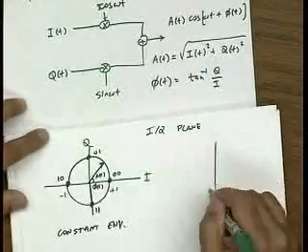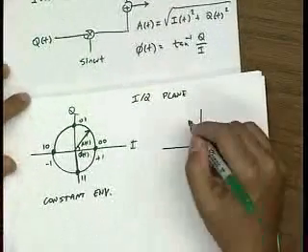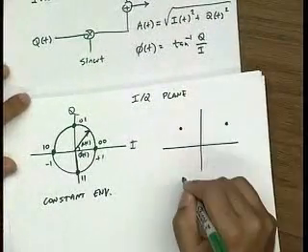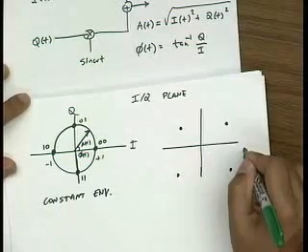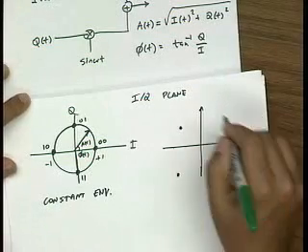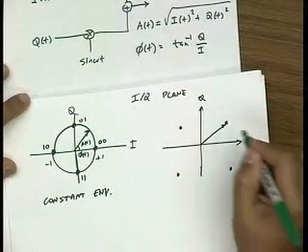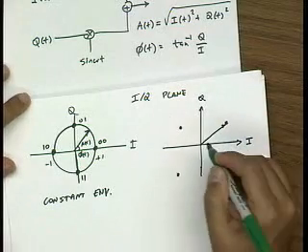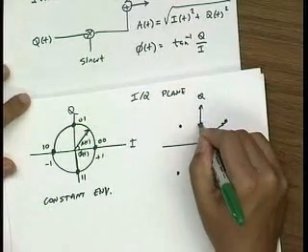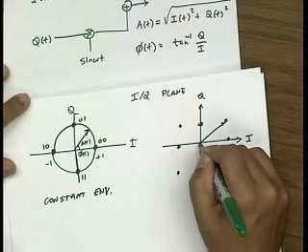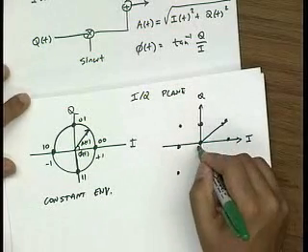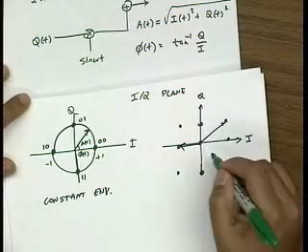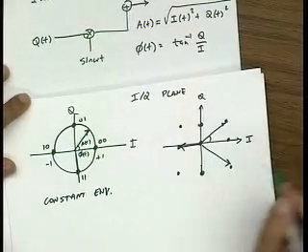I could also do a more complicated modulation. For instance, I could send these 4 points on the IQ plane, and now you could see that the amplitude also changes. For instance, let me add some more points to try to pack more information. So you could see that now the envelope changes depending on what bit I send, and so does the phase.